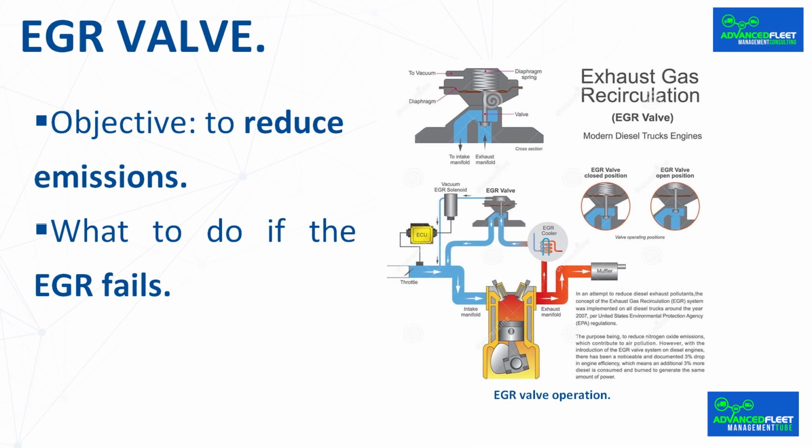In addition, if left open, carbon builds up not only in the EGR but also in the intake, reducing the flow of air into the combustion chamber and causing a loss of performance, as happens with the arteries of the human body and cholesterol. If combustion is poorer, more carbon is produced, so it is a case of the fish that bites its own tail.